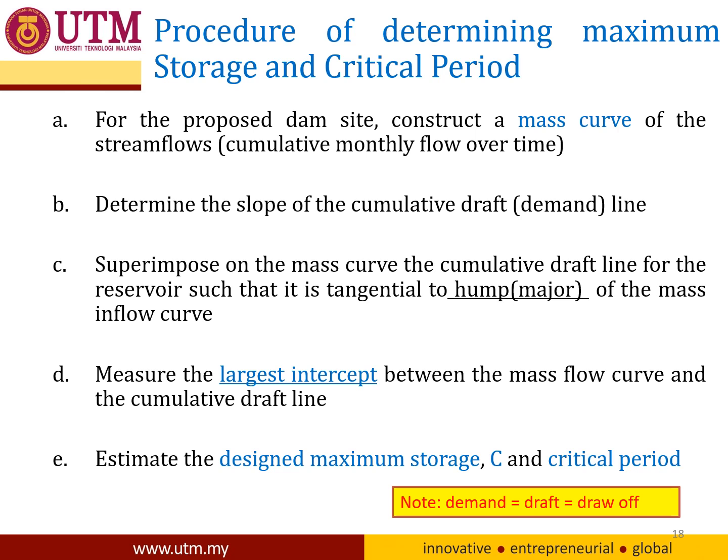Okay, so for our case as engineers, we need to determine the maximum storage capacity. We need to design, or we need to check whether the storage is sufficient for the demand. And also the critical period. What is the critical period? It is where we analyze at what time the water is not sufficient.